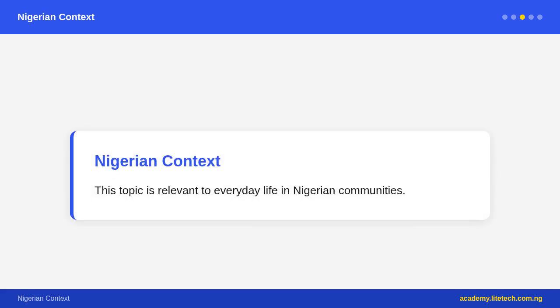Types of gears include spur gears, which have straight teeth parallel to the gear axis and are the most common type, used in clocks, machines, and automobile gearboxes; helical gears, which have angled teeth that engage more gradually and smoothly, producing less noise and vibration than spur gears, used in car gearboxes and industrial machinery;